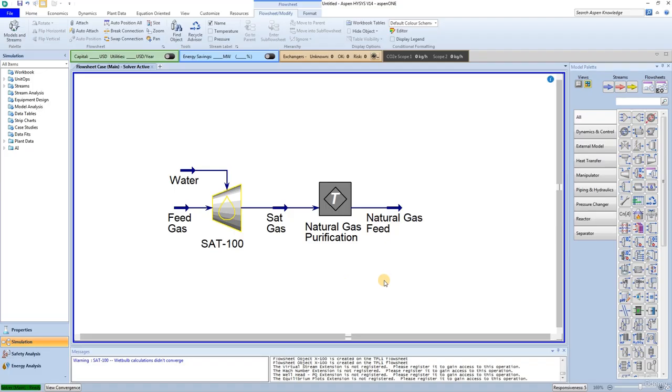Task 3. Pre-cooling train. After the natural gas stream has been dehydrated and sweetened, it can be fed to a pre-cooling train. This train will be modeled as a series of HYSYS cooler operations to successfully lower the temperature of the stream. A parallel cooling train is also created to handle the mixed refrigerant coolant. This mixed refrigerant coolant will be used further downstream in the process to help generate the LNG product.